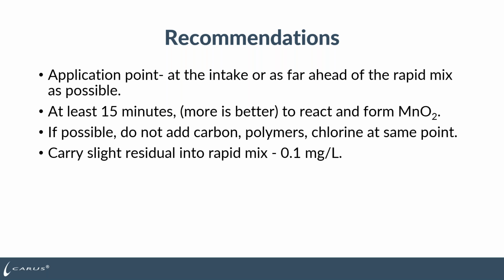Ideally, when you feed permanganate, once you're feeding it in the plant, carry a slight residual either into your rapid mix or to the end of your flocculators if you're feeding in the plant so that you know you've maintained permanganate residual for that set amount of time that you have.